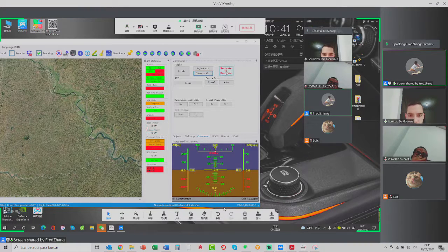Okay? For the command, we only use adjust the altitude and recover the altitude. Okay. And navigate to emergency waypoint. Okay. You only use these three functions. Adjust the altitude and recover the altitude mean that during the flight, if you want to change the flight height, you can use this function. Okay. Adjust the altitude: increase the height or lower the height.